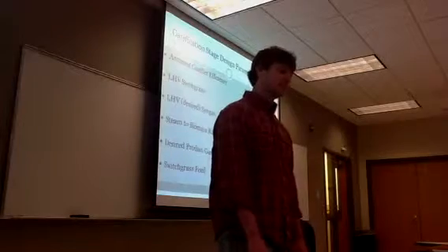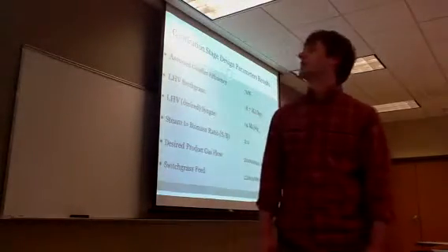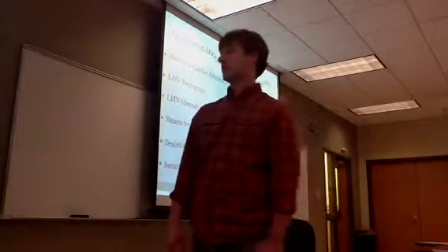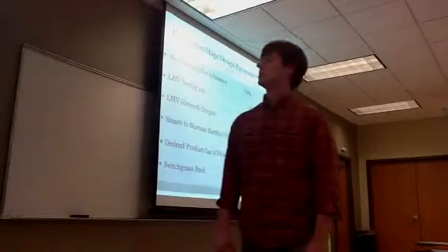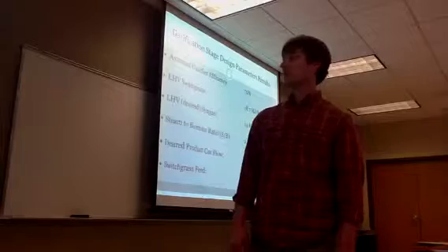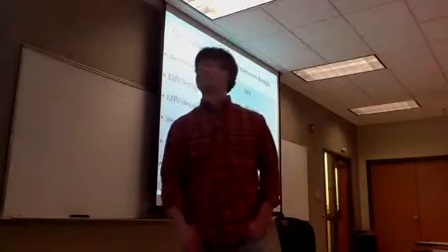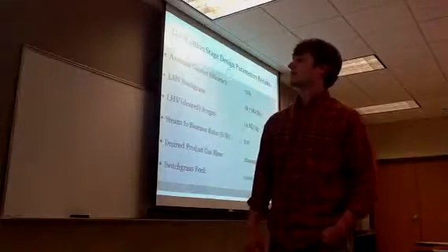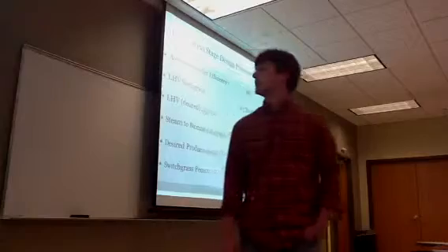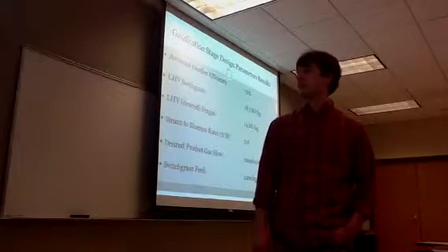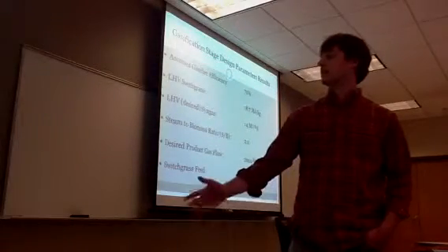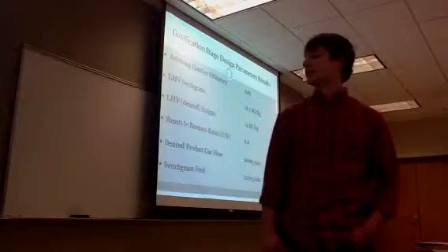Next, for the gasification stage, some of our specifications: we assume the gasifier efficiency, through our research, is about 70%. The lower heating value of the switchgrass, from the ultimate analysis, was 18.7 megajoules per kilogram. The lower heating value of the syngas, produced from steam as opposed to air or oxygen, is 14 megajoules per kilogram, which is a medium lower heating value. The steam to biomass ratio was 2.0. Our desired product gas flow again was 2,000 kilograms per minute, and the switchgrass feed, through our mass equation, was 2,200 kilograms per minute.